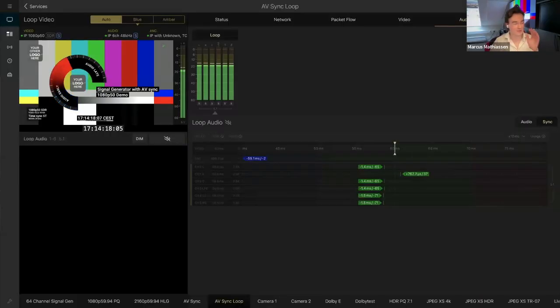Yeah. So let me share my screen again here, and I can talk you through it. Like Joe said, we showed this off at NAB and IBC this year. This is basically 440 taking its signal generator, which you can have 5 of, and we can embed timing metadata into the signal, into the video, and also into each audio channel. And then you can send that signal through your pipeline. It doesn't need to be the same 440. Back to a 440, and we can decode the amount of time that is taken to send the signal, and also the amount of skew that has happened on the RTP timestamps through that path.